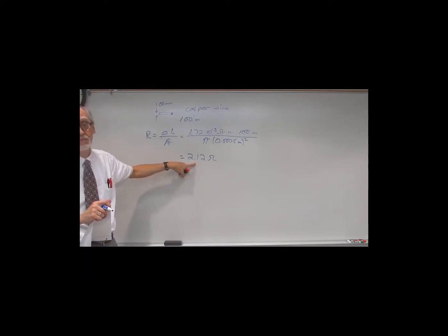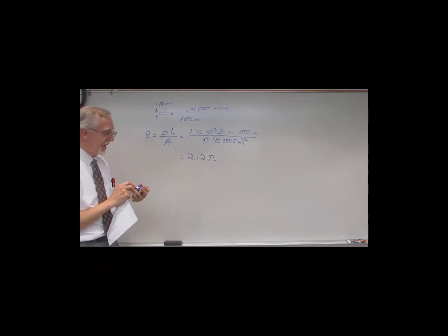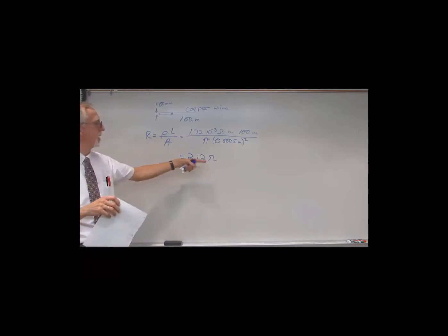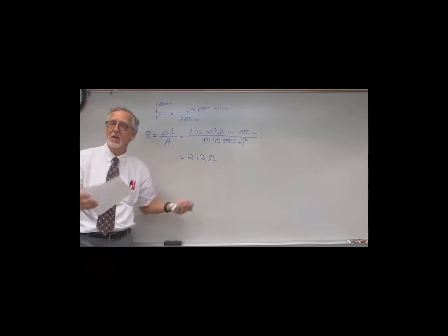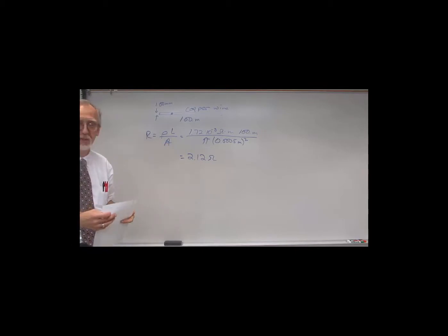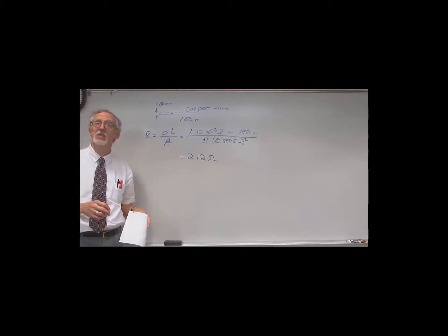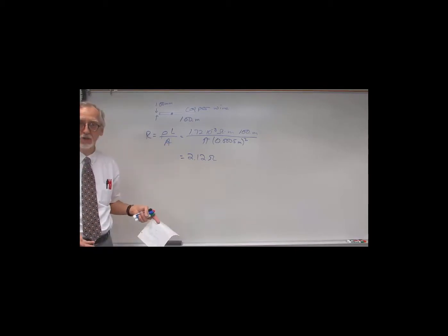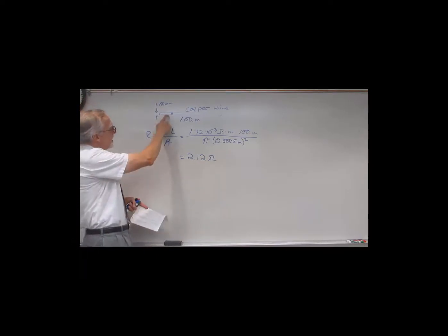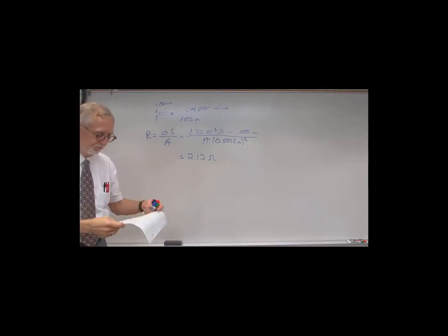So, for a very, very long piece of wire, we still only get a resistance of a couple of ohms. So typically, any time that we have a circuit with a resistor of 10 ohms or 100 ohms or 1,000 ohms or something like that, the resistance of that resistor is going to be much, much larger than the resistance of the wires that we'll be using.